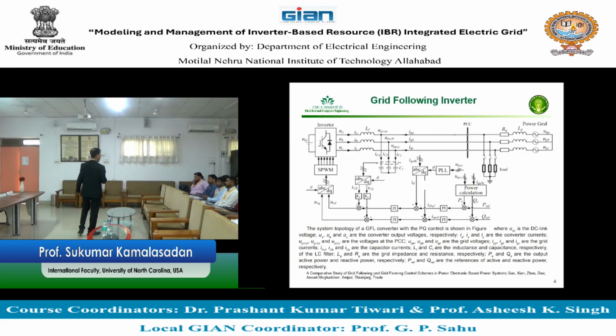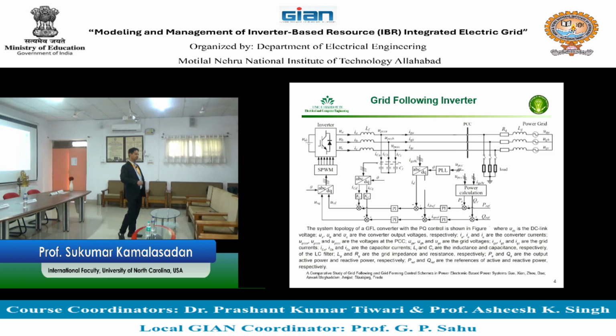Not many energy sources are voltage sources. For example, photovoltaics are not considered a voltage source because they are a current source. Ideally we say the current has infinite capacity and pushes the power, so it's controlling the power through current. But if you are working with, for example, a battery, then you will consider that as a voltage source. So the topology we discussed is as a voltage source.